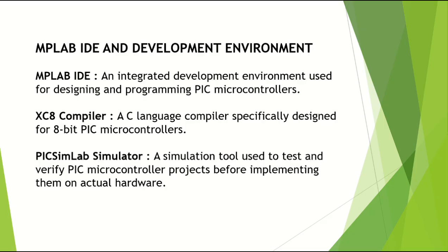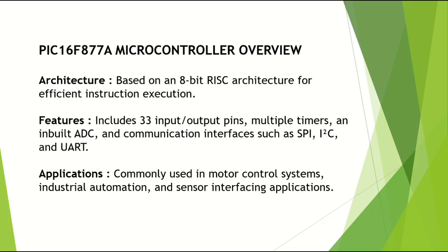PIC16F877A microcontroller overview. Its architecture is based on 8-bit RISC architecture for efficient instruction execution. Features include multiple input-output pins, multiple timers, an inbuilt ADC, and communication interfaces such as SPI, I2C, and UART. It is commonly used in motor control systems, industrial automation, and sensor interfacing applications.